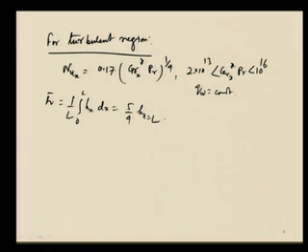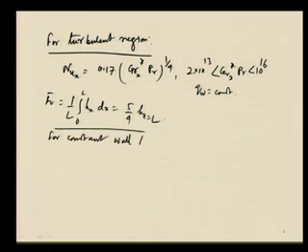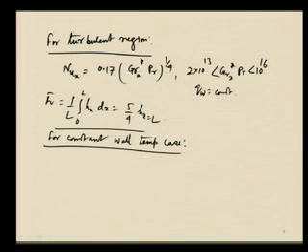Now, one thing, if we try to analyze the difference between the isothermal case and the constant wall heat flux case, then for the constant wall temperature case, what we have seen is that Nusselt x is equal to C into Grashof x, it is not modified, into Prandtl to the power m. That we have just seen.